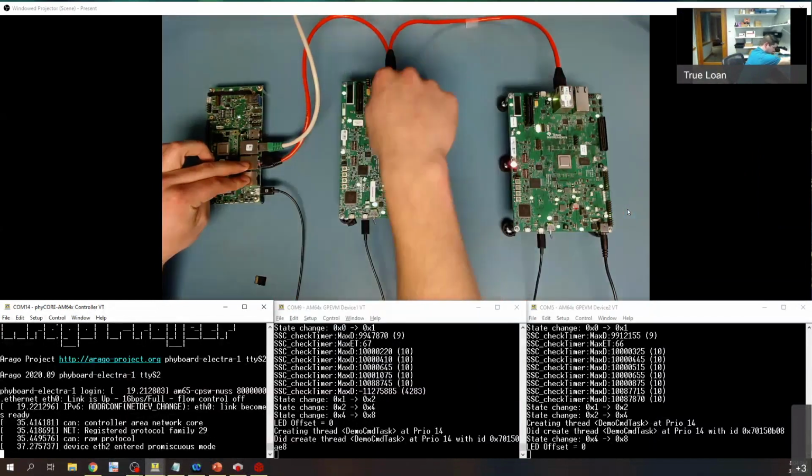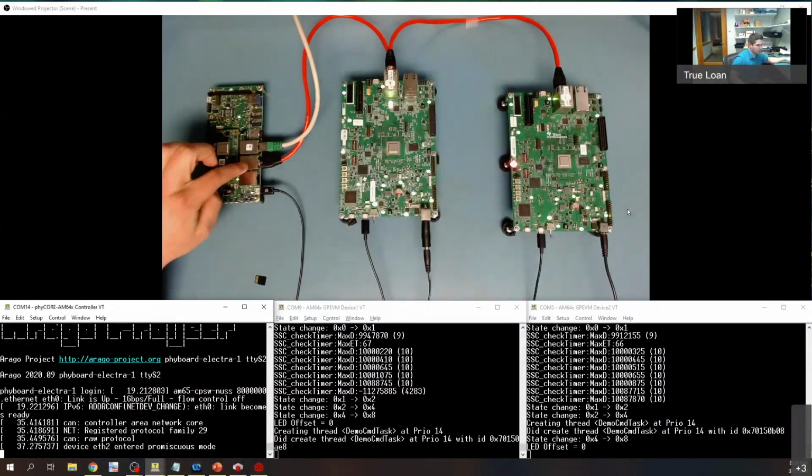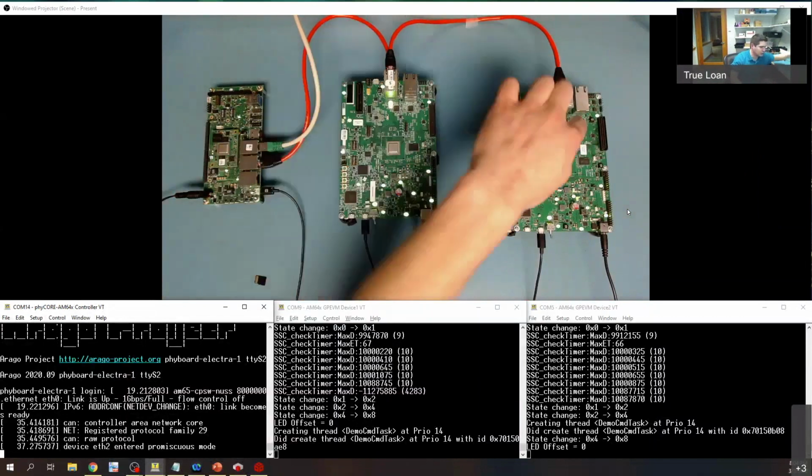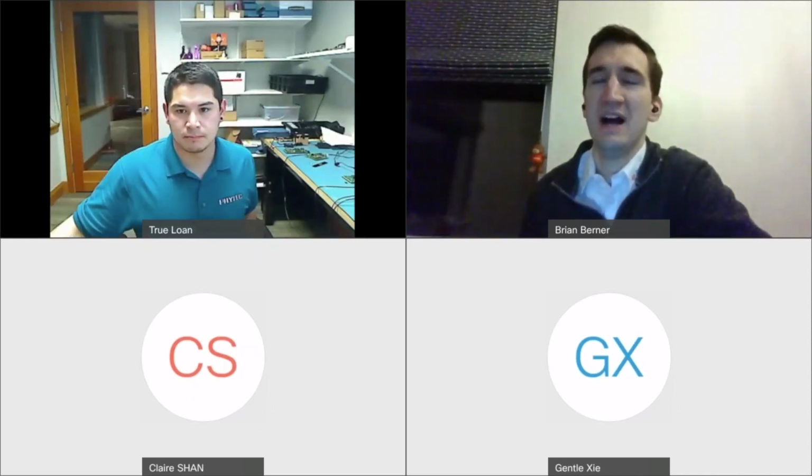I'm utilizing PRU Ethernets here on the secondary boards, but here they're just operating as any other Ethernet port. You could utilize any Ethernet port. I could have used the CPSW Ethernet port to daisy chain the network as well. And then I have the Pinger Lite, which could give you options of getting more Ethernet ports. So the maximum with both CPSWs and the PRU, I think, is 5. At that point, you would have to switch to an Ethernet hub. Right.